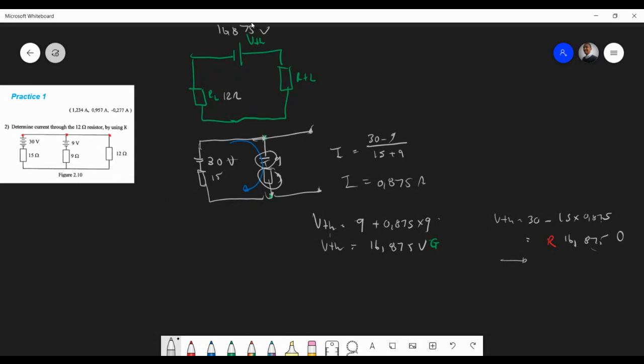So I first found the voltage drop across here. So we have to essentially add them up. But if you're dealing with this branch, you're coming over here, you're going to have to subtract the voltage as we go that way. And in this case here, it's actually the total voltage across the branch. So obviously this is the easier approach. Are we happy with this? So we found the voltage. We're basically adding a voltage here and a voltage here.